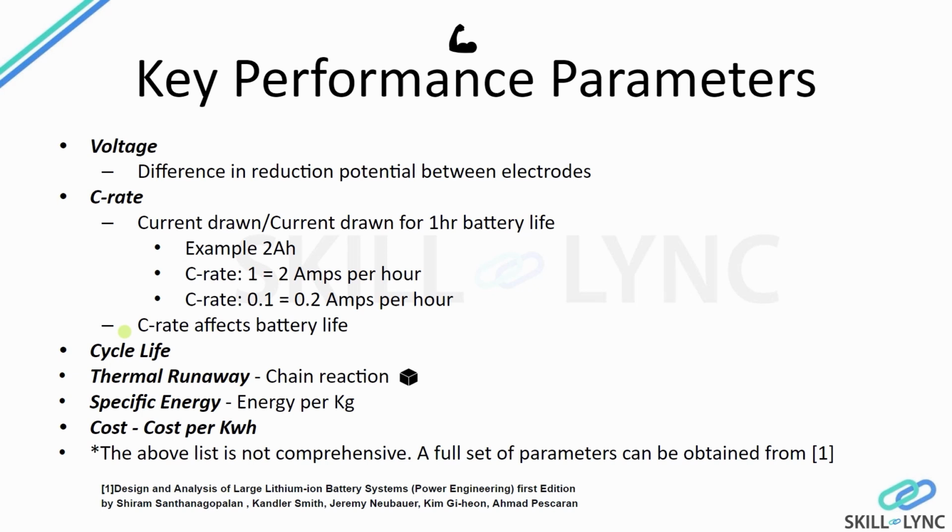When a battery goes from fully charged to some percentage of usage, that percentage of usage is what you call depth of discharge. So if 80% of the battery life is consumed before you charge it again, then that's essentially one cycle where the depth of discharge is 80%.